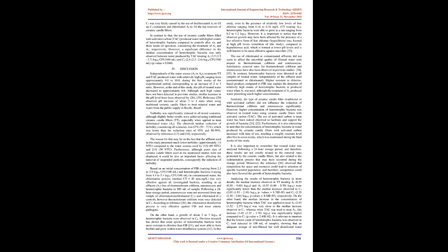This resulted in a significant difference in the median concentration of heterotrophic bacteria observed between water produced using TT to treat A2, 0.6, 0.4 to 0.7 log10 CFU/100 ml, compared to C2, 2.4, 2.3 to 2.6 log10 CFU/100 ml, p-value equals 1.76 times 10 to the power of -4, and between water produced by TT treating A1, 5.3, 5.2 to 5.3 log10 CFU/100 ml, compared to C1, 6.7, 6.5 to 6.8 log10 CFU/100 ml, p-value equals 1.63 times 10 to the power of -4.